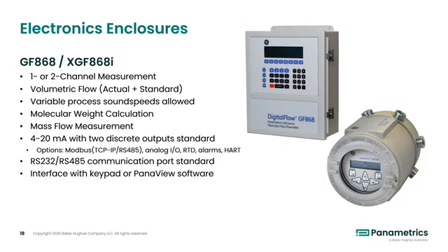This has a full keypad with soft touch buttons, which makes interfacing a breeze. From analog inputs and outputs to alarm relays, pulse or frequency totalizer cards, and even Modbus, HART, and Foundation Fieldbus digital cards, our GF868 can be loaded with up to 6 additional option cards to expand your data capabilities. This standard enclosure can also be mounted inside of an explosion-proof or a flame-proof enclosure as required by your site's requirements.